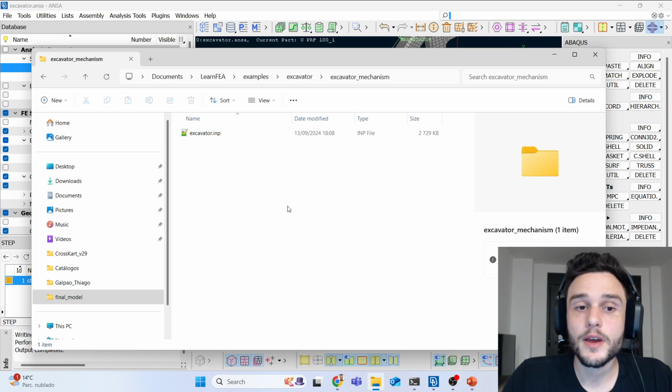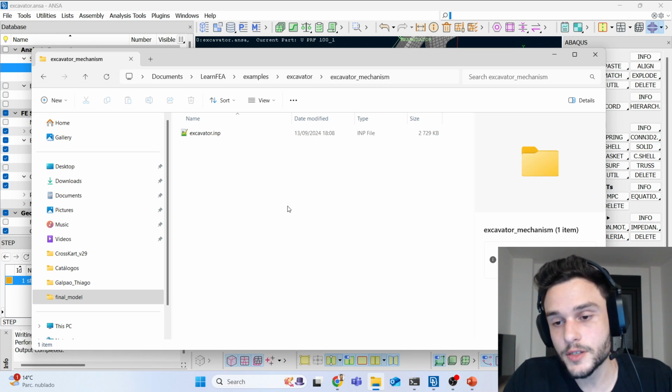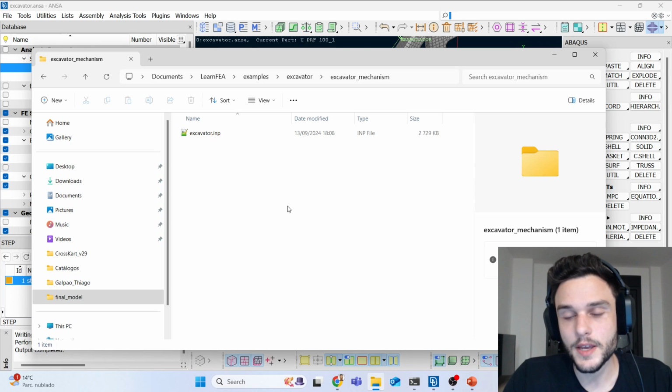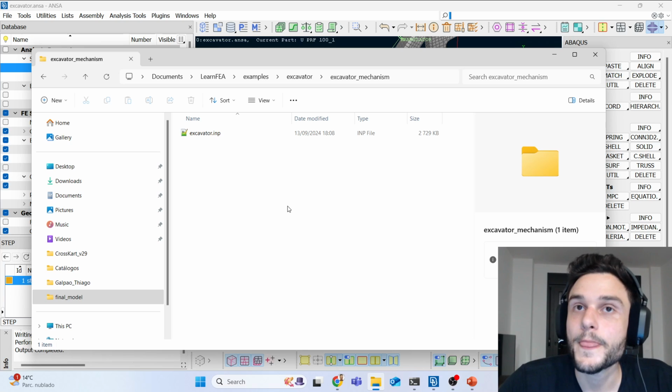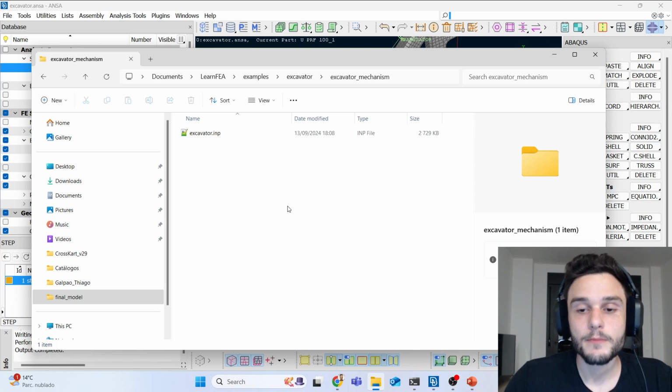Well, to run it, you can open up the Abaqus CAE application, just like we did before. I showed it in the first video, I guess, of this series of videos. You can import the module, create a job, and submit it. But to be more practical, we can do this by CMD command. Right-click and open in terminal.